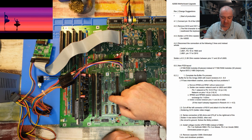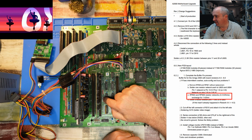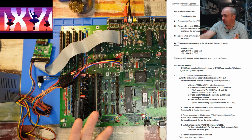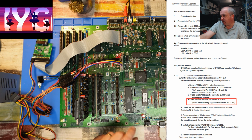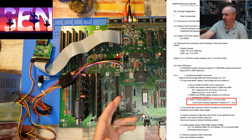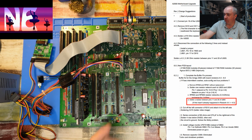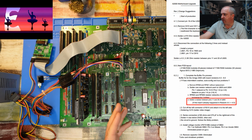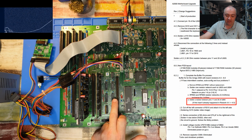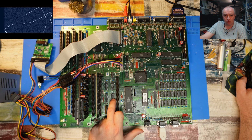So next one then is changing those two resistor packs, RP903 and 908, changing them to 1K. And then after that, actually, there's that other mod again. Solder resistor between pins 11 and 20 of U605, if this hasn't already happened in rework between 4.4 and 4.5. Okay, so again that wants us to go and fit 3.3K between pins 11 and 20 on that one, on that bus address strobe signal.